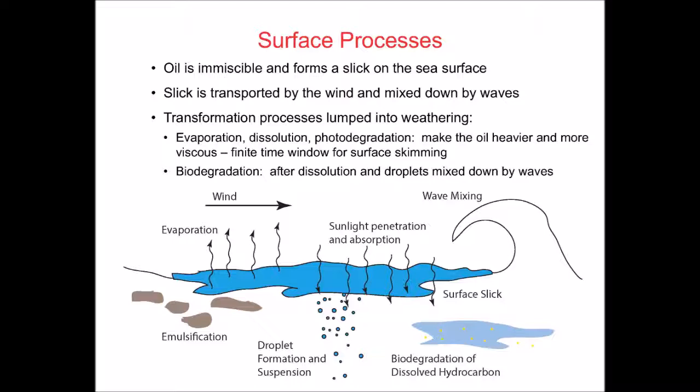So when we use chemical dispersant subsea, we're trying to spread the oil out so much that it maybe doesn't even reach this sort of state, or if it does, it's already dispersed. If the subsea dispersant addition doesn't cause that to happen or is not being done, and we do have surface slicks, then we have the option of spraying dispersant on the free surface from an airplane, which is the more traditional way that dispersants have been used historically before Deepwater Horizon.